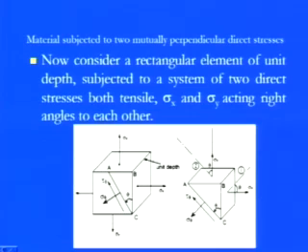So cut the plane, and we have two different regions. At AC we want to check sigma theta and tau theta, while on the other two planes we have sigma x and sigma y. We can resolve these as sigma x cos theta, sigma x sin theta, sigma y cos theta, and sigma y sin theta, and so we resolve these stress components in terms of sigma theta and tau theta with sigma x and sigma y. On these planes only normal stress is there, there is no shear stress component.